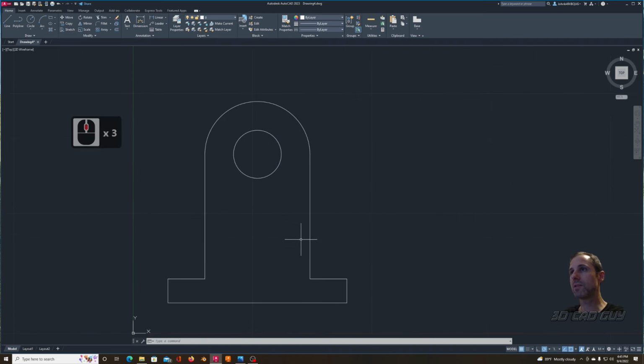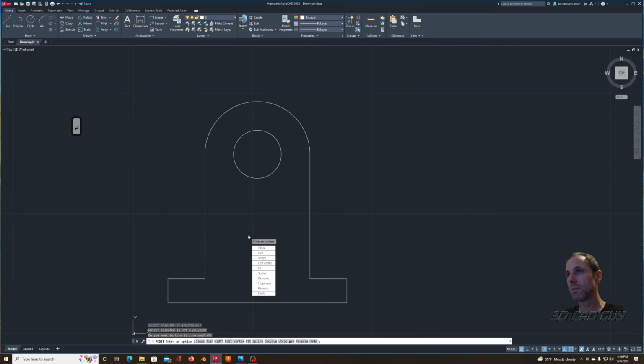Now, after we're done with this, this is basically all in segments. In order to work in 3D, you have to create it in a polyline. But the best way to do that is after the fact. So when you've got this all set up how you want it, trim and cut and do all of the offsets, whatever you're doing to scale, then you can just simply type in PEDIT, PE. Select any of the lines. It'll notice that it's not a polyline. It'll turn it into one automatically if you just hit return when the default is up.